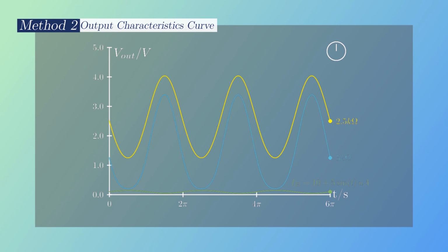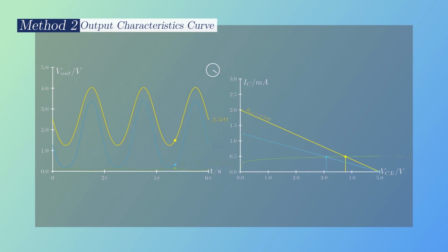I think this is a question that requires a bit of thought, but if you can figure out the answer, that'll set you up in good shape to understand concepts such as the DC operating point and biasing of BJT amplifiers. A hint is to look back on the previous scene, specifically at the region that the intersection point is located along the 5 kΩ resistor path when the base current is high. See if you can figure out why.